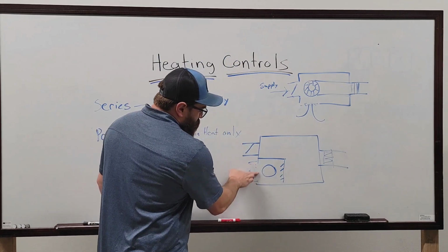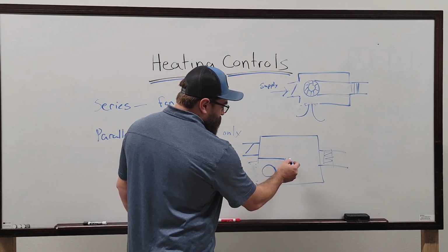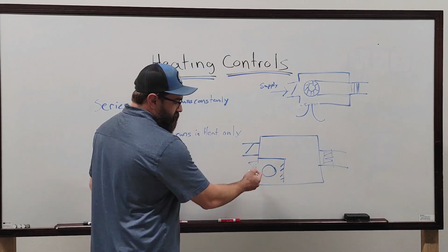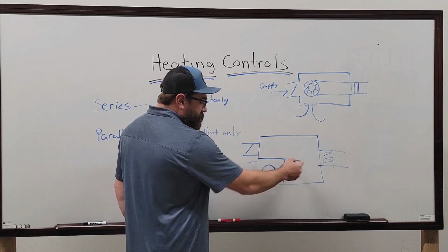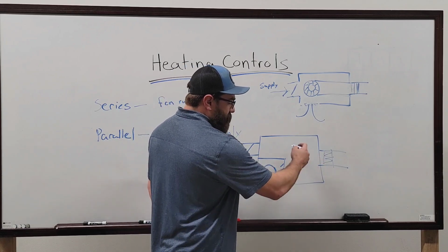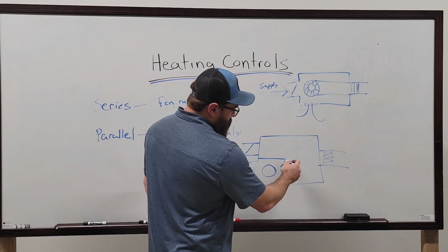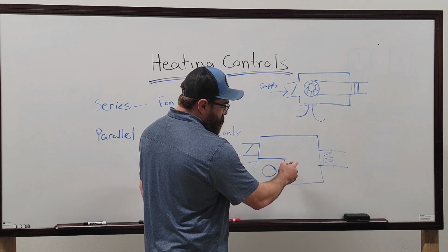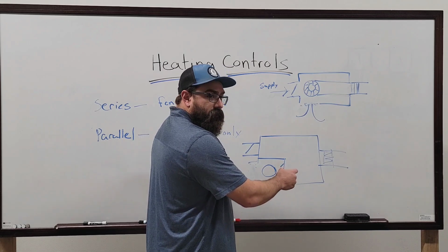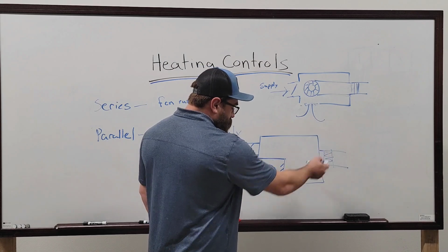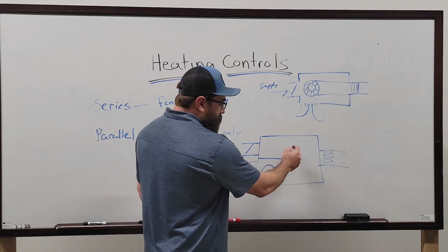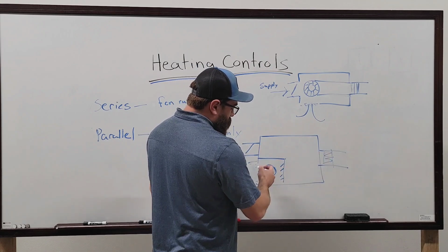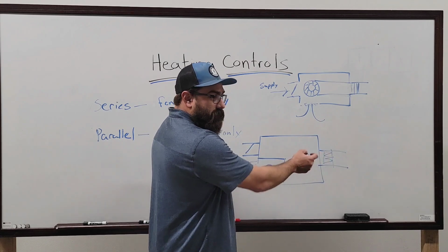But the way a parallel box works is you have two separate cabinets, basically. They're parallel to each other. You have a fan cavity and a supply cavity. Either one can pressurize the cabinet. And then what happens is the fan will have backdraft dampers on it. That way you cannot push air through the fan out into the plenum. So either the supply duct pressurizes the cabinet or the fan pressurizes the cabinet.